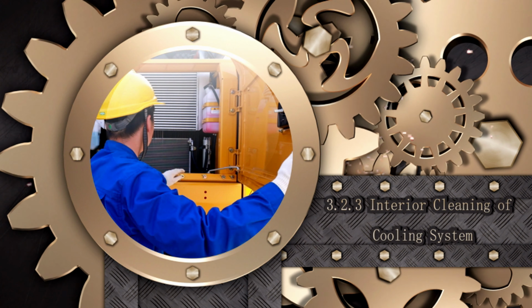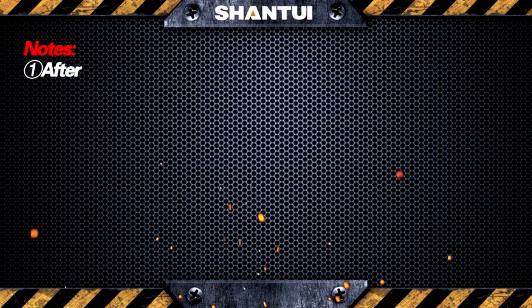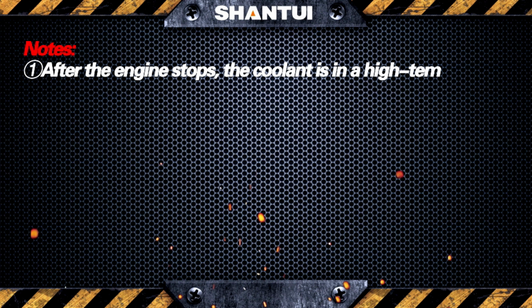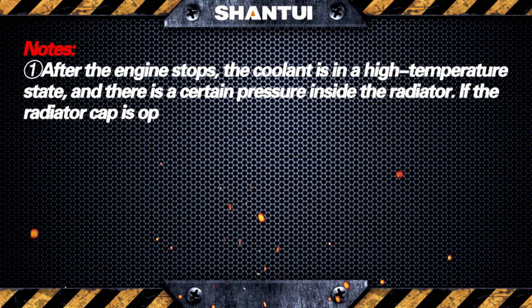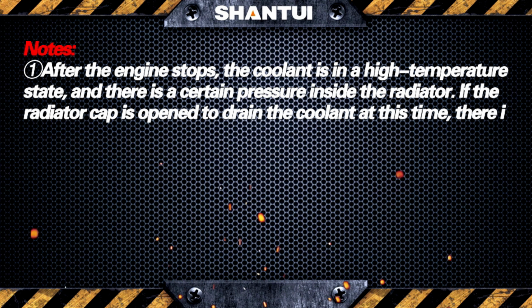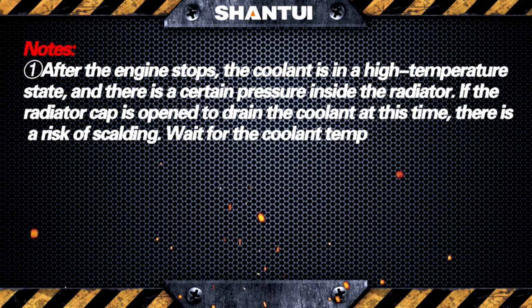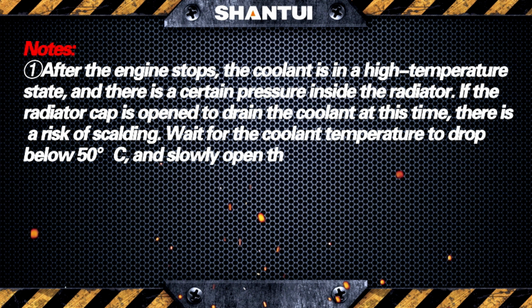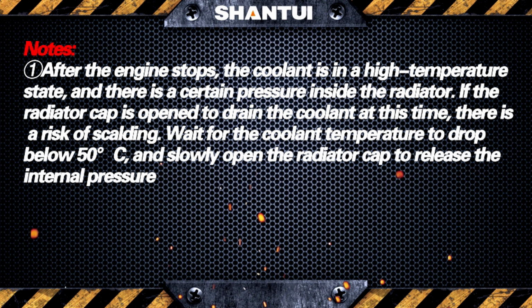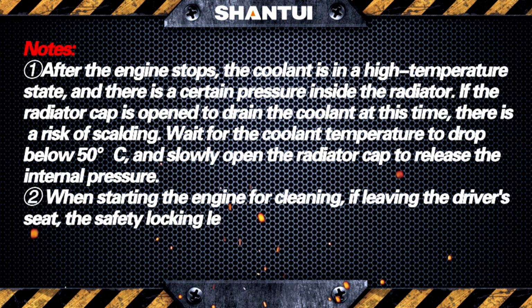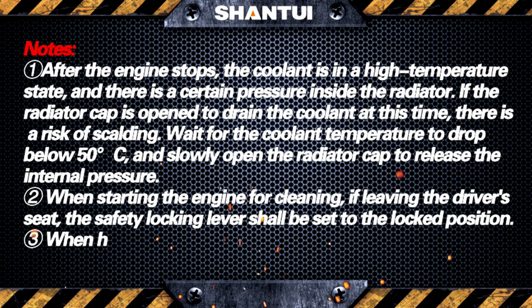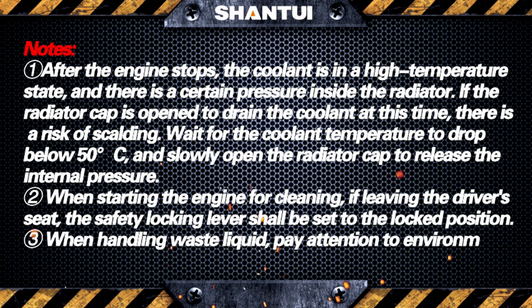Interior cleaning of cooling system. Notes: 1. After the engine stops, the coolant is in a high-temperature state, and there is a certain pressure inside the radiator. If the radiator cap is open to drain the coolant at this time, there is a risk of scalding. Wait for the coolant temperature to drop below 50 degrees Celsius, and slowly open the radiator cap to release the internal pressure. 2. When starting the engine for cleaning, if leaving the driver's seat, the safety locking lever shall be set to the locked position.